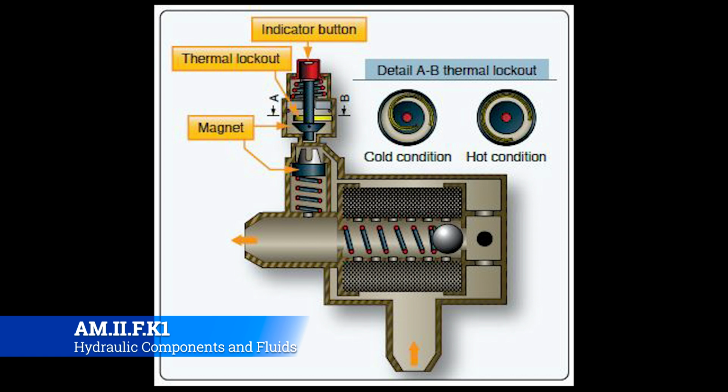You're going to have to take that filter out, replace it. Usually, we'll do a flush of the system to get anything that could potentially be in there, any kind of trash, out, and then recharge it and do a quick maintenance operational check, or MOC. You're going to hear me say MOCs a lot because we're going to start talking about systems. You're going to MOC the system, and then if everything passes per whatever AMM task you're working to, you'll return to service, and it's no big deal.